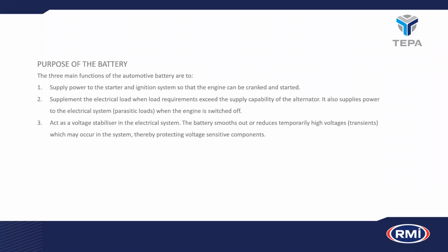Now, the battery is a typical absorber of those, but in the event of the battery being flat and you're doing a jump start, that battery is not performing its task in that manner, and therefore the purpose of it is that you put on all those auxiliary systems to absorb any spike loads that may come through at the time.